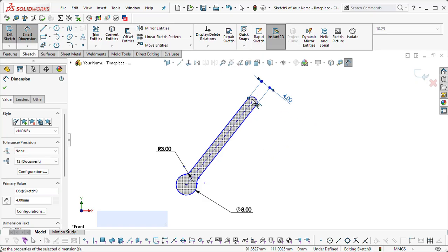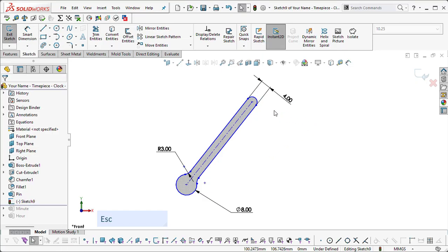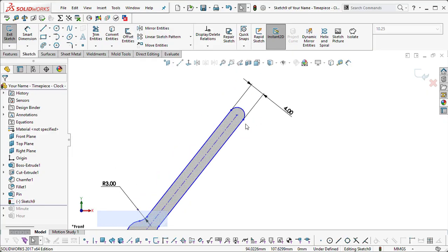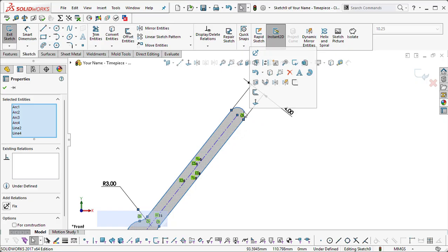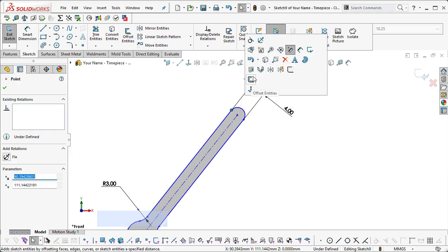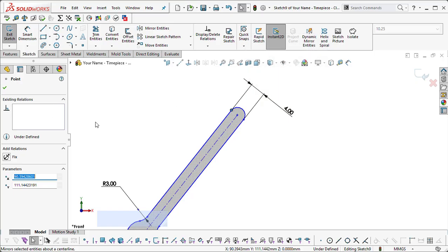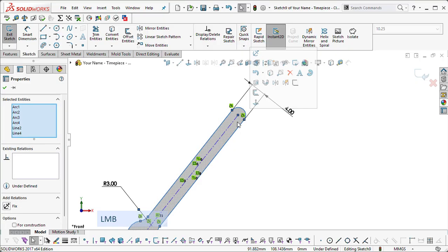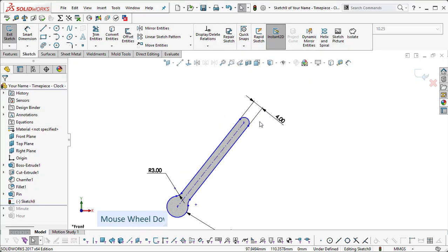I don't need to dimension the circle because it should be linked, but I guarantee you it's only got one tangency. So we need 2 tangencies. So if I click inside the sketch, you'll see there's one tangency, there isn't one over there. So if you select that vertex, you'll now get in the context menu a make tangent item. Often it doesn't say anything in here, but if you click in again, you'll see it's got two tangencies.